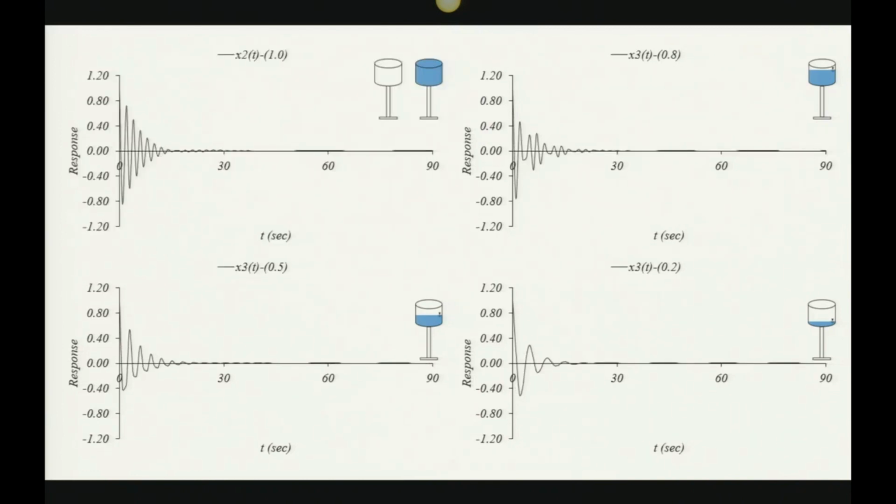But to compare the translation, which was the second degree of freedom for the single mass, and this is the third degree of freedom for the other three masses, we can see a similar behavior. We can also state that in the text, if you notice, they do not really consider the rotational degree of freedom for the structures when they do the analysis, and for the mass moment of inertia, they just consider 0 and 0. So probably it's because they don't really make much of a difference, and that's what we thought.